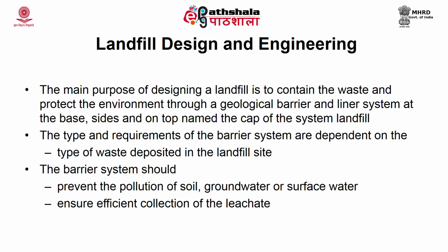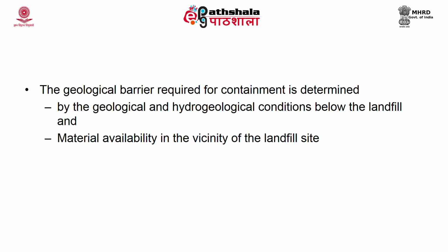The barrier system should prevent the pollution of soil, groundwater as well as surface water, and it should also ensure efficient collection of leachate. So, you have to keep these two criteria in mind when you select a barrier system. Now, a geological barrier is determined based on the geological and hydrogeological conditions below the landfill and in the surrounding vicinity.